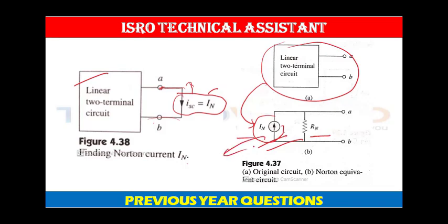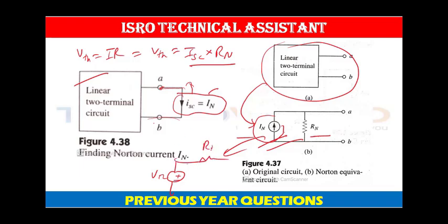If I have to convert this into VTH and RTH, how can I calculate? We know that V equals IR, and therefore VTH is equal to the Norton current ISC or IN into the resistance RN. We know that RN is equal to RTH. This is how we can calculate Norton from Thevenin and Thevenin from Norton.